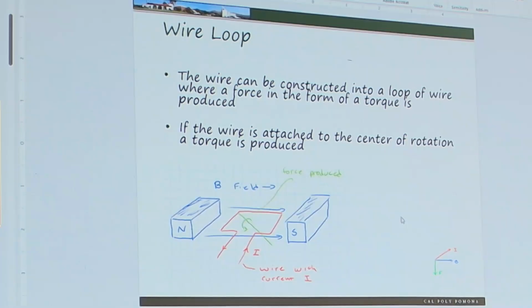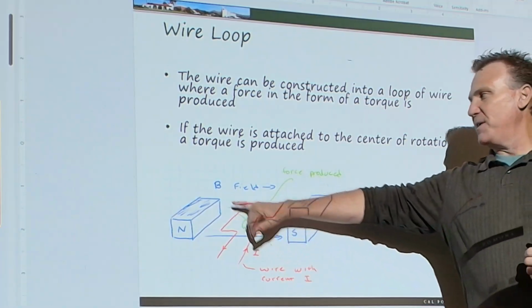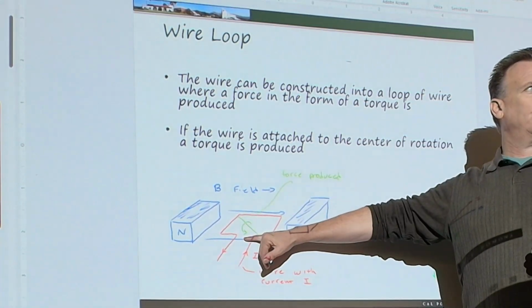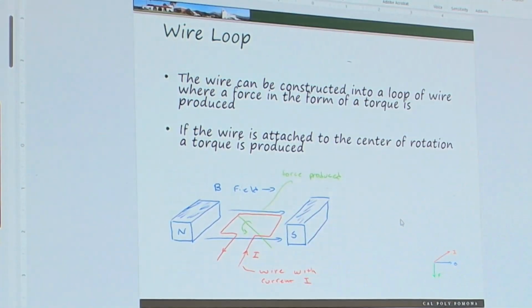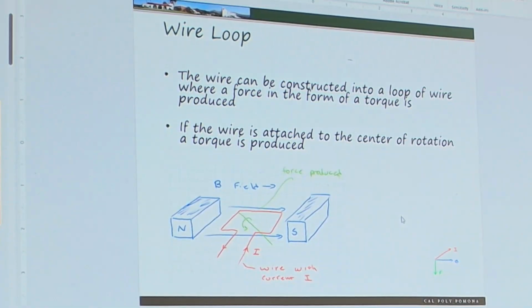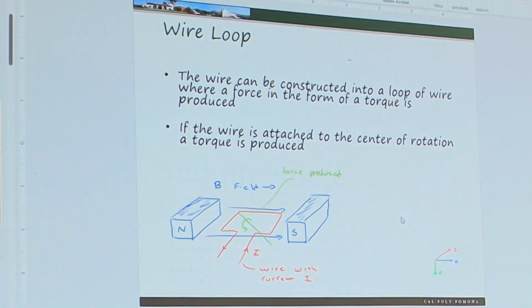Torque and current are proportional based on this B field and the number of windings. So if I need to move a large force in a motor, that requires a large what, electrical? Current. Not more voltage, more current.